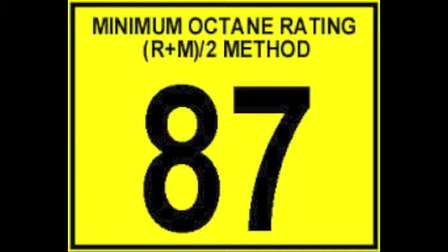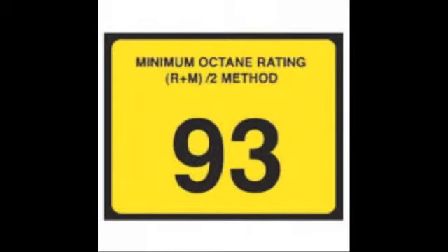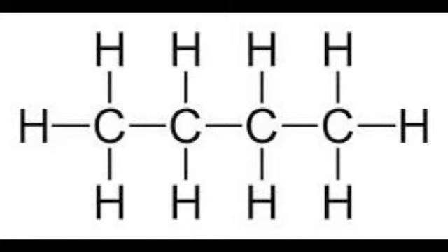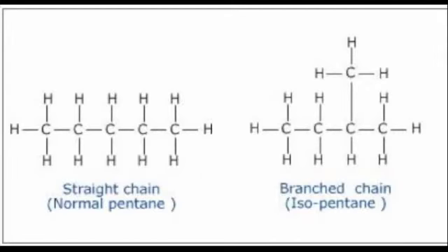The higher this octane number, the more knock resistant the fuel is, and the more compression the fuel can withstand, which results in a more powerful explosion after ignition. A fuel's ability to prevent knocking is based on its ratio of branched chains to straight chain hydrocarbons. Higher levels of branched chains in a fuel are more efficient for high-performance engines, such as sports cars or race cars.